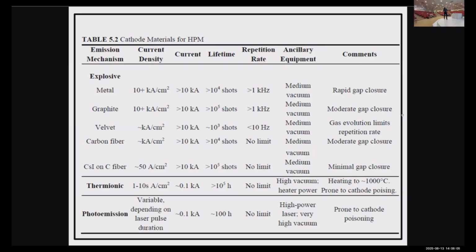Another thing about this explosive electron emission, you can have an environment with a medium vacuum. So you don't have to have your tube baked and sealed for vacuum. That is for lower power microwave tubes, where if something happens you just replace them, since you can't open them. It's going to be very challenging to seal the vacuum back. But for high power microwave, especially at lab scale, we're always going to open up the system, break the vacuum, do something, and then put it back.